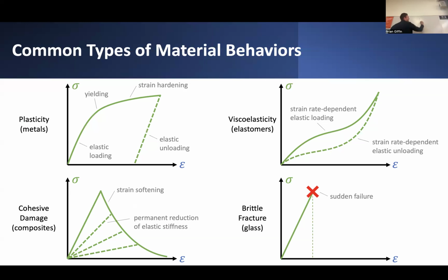and it might initially look like it's being deformed plastically, like this first curve on the top half here. But then over multiple cycles of loading, these hysteresis loops start collapsing. In effect, what you're observing is two different phenomena happening in combination, both some amount of plasticity and some damage. So as this dimension shrinks further and as the apparent stiffness of the stress strain curve as you elastically unload it is decreasing, then I would call that damage. But in general, you have to distinguish how much of this is plasticity, how much of it is damage. And those two things can be combined and integrated into one model that is sometimes called a damage plasticity model. Very complicated models, but you can have both of those things happening at the same time.